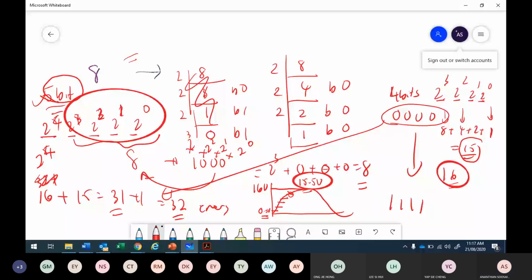You will have a code for 15.5 if you use 5 bits. But if you use 4 bits, 15.5 won't have a code. So what will 4 bits do? The 15.5 is registered as 15 volts, because 15 volts has a code. So this is bad. So how do you improve the quality of transforming from analog to digital? Increase the number of bits.